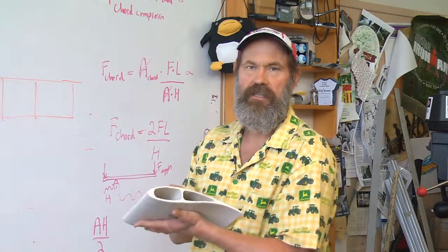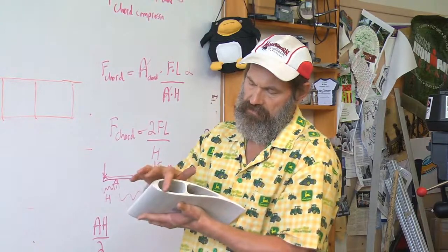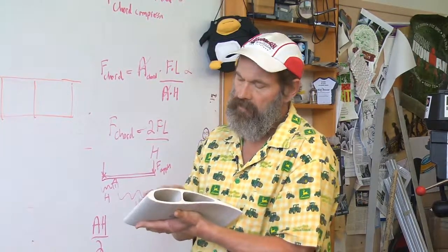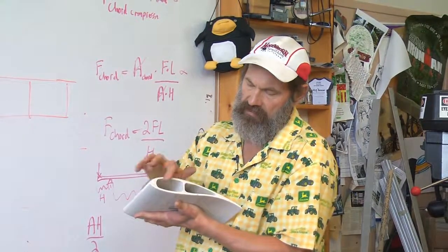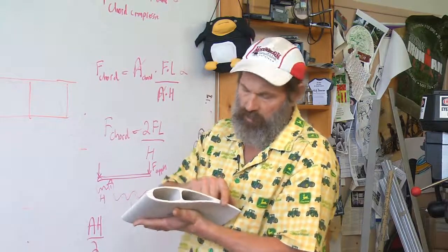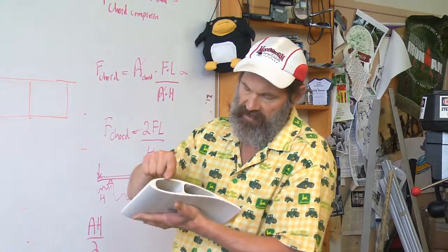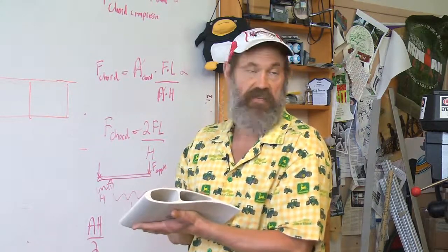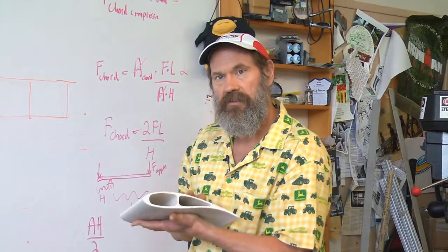Do we need it to be that stiff? It might be much stronger, but do we need to be that strong? Versus, look how manufacturable this is, and I do have a triangle here anyway. Well, this triangle automatically, by default, ends up supporting this rectangle, where adding diagonals does absolutely nothing for me, except add cost.